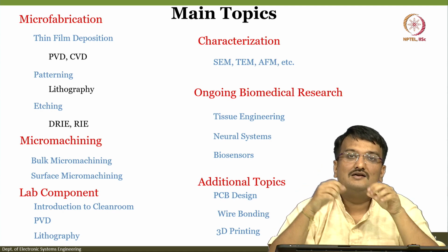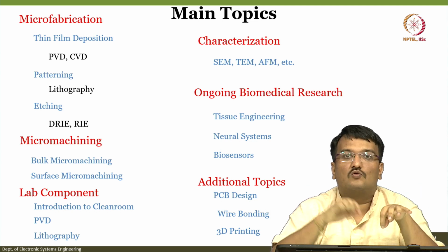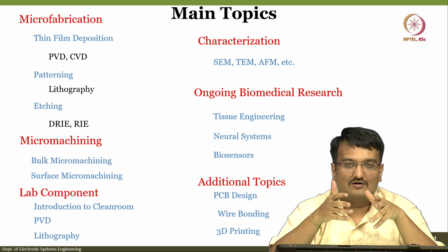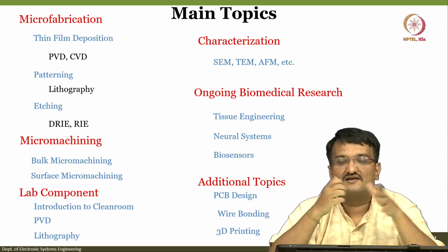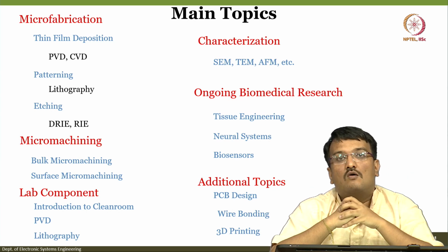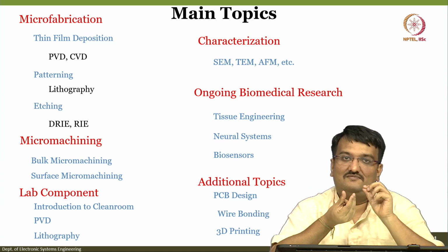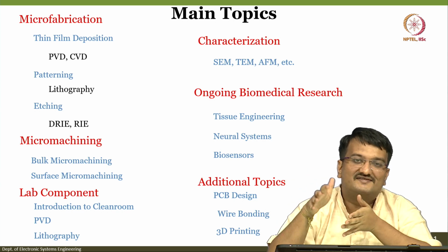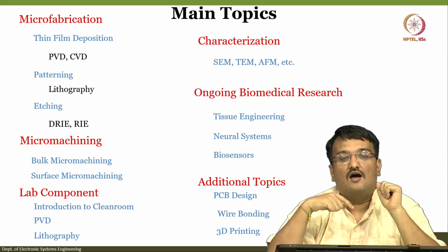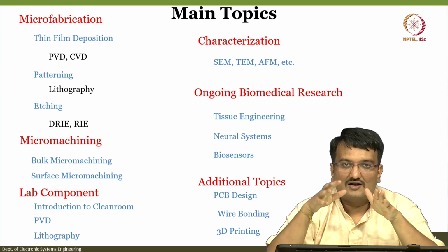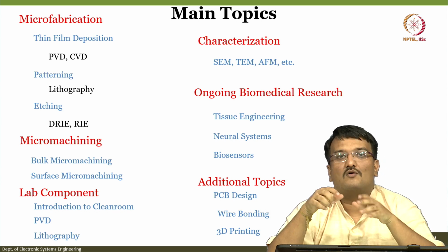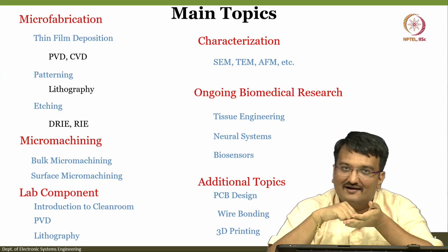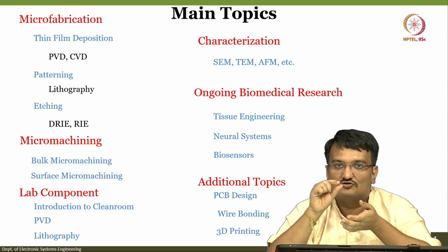Instead of using multiple wires going from one module to another, there are high chances that you might not get a proper connection or robust communication interfaces. So how can we mitigate that? By making a small PCB. It will be covered in this course how analog electronic modules are designed and customized for your application. Further, once you have the contact pads, they should be wire bonded, so that all your sensor interfaces are properly intact. When you want to take any electrical signal from your chip to the outside world, it should be wire bonded.